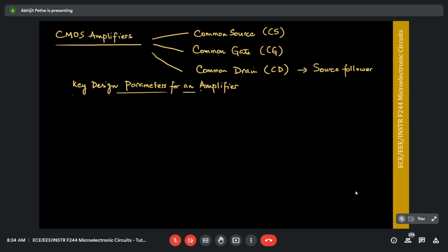If I want to pick an amplifier, what are the things I need to look at? Based on what you might have picked up in the last few classes of this course, what do you consider the various design parameters of an amplifier? What will you design for? Ideal gain, R out and R in.